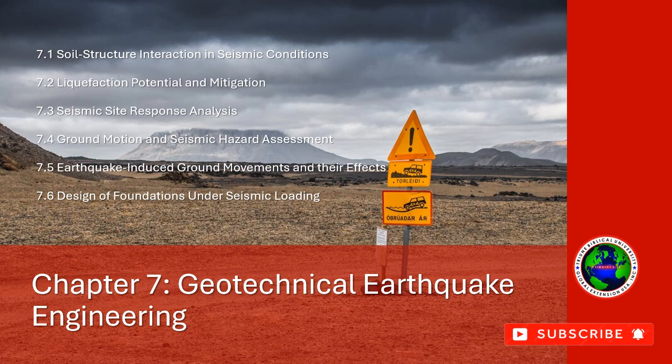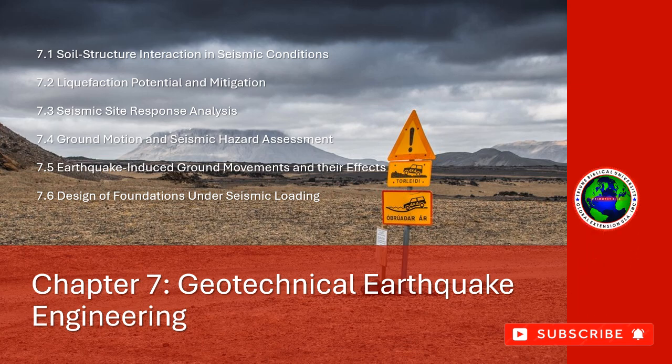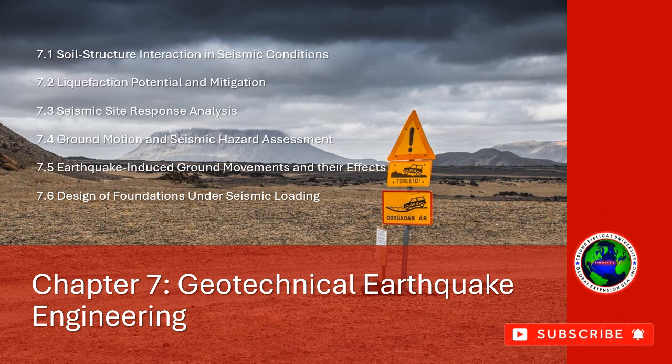Steps for nonlinear analysis. Nonlinear material models: nonlinear models, such as the equivalent linear or fully nonlinear methods, are used to simulate changes in soil stiffness and damping during the seismic event. These models allow the soil shear modulus and damping ratio to vary depending on the level of strain induced by the earthquake.